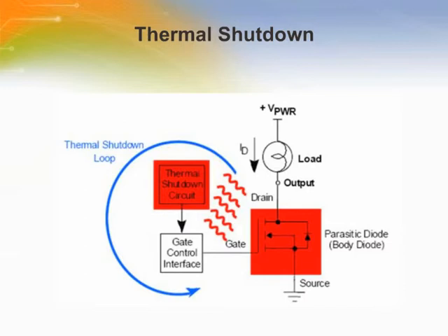The power output switch is usually the only element of the IC that is thermally protected, since the power switch is normally the primary source of heat generation. Thermal shutdown is usually incorporated in a power switch along with current limit protection. This combination will allow the switch to continue to operate in an output current limiting mode so long as the thermal operating limit is not exceeded.